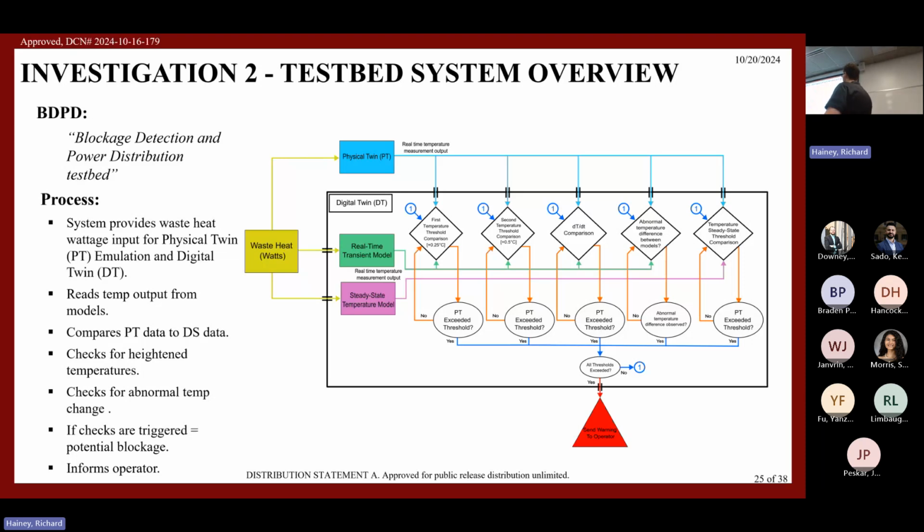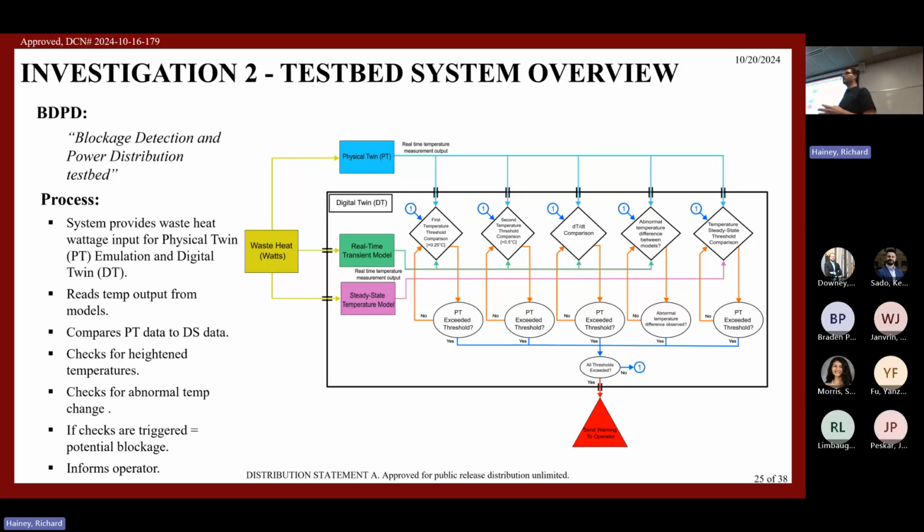And the last one is just a number of over temperature comparison, as I explained. It just uses thermodynamic heating equations to determine what the maximum possible temperature you would get in your coolant based on your heat input. This is, of course, assuming that the coolant has maintained its integrity or flow. And if it hasn't, you'll see an over temperature in this case. That's also one of our checks.